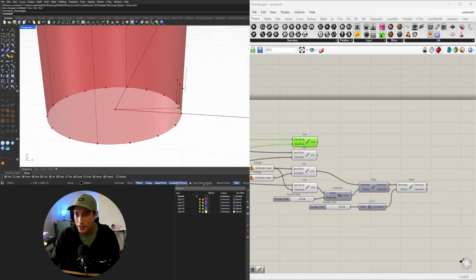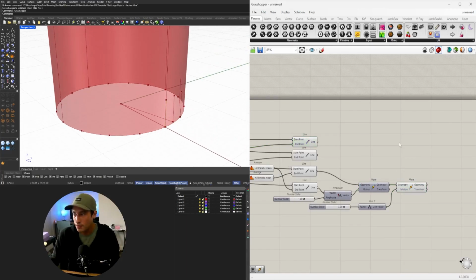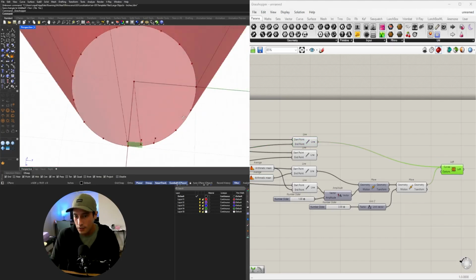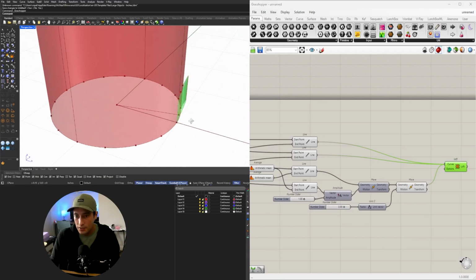And the way to create that tile is starting here, connecting here, and that next one doing the same thing. So we can do this two ways. We can loft this, starting here, continuing with this one. So holding down shift, I can add another input. And holding down shift, I can add another input.